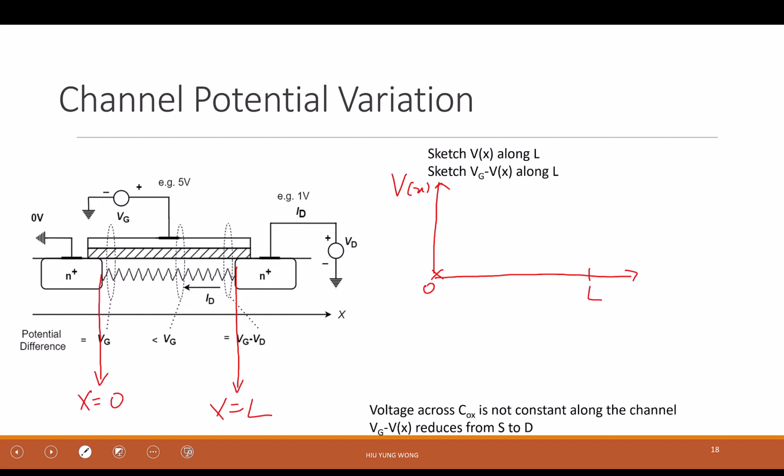Sometimes we need to think, but we only talk about potential. There, we need to consider the doping, the Fermi level, but we don't need to be so detailed. The point is that we understand the potential increases from the source to the drain. That's the main point. Whether it's linear, quadratic, exponential, whatever, depends on the math.